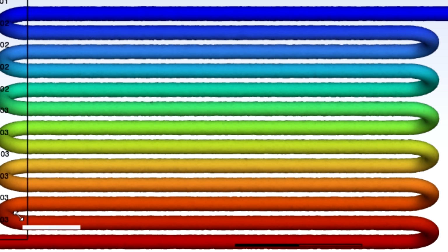So with this one, we'll conclude our today's analysis. This is a very simple analysis of condenser heat exchanger. In this case, we have provided freon gas at the inlet at a higher temperature of 75 degrees centigrade, and finally at the exit, it has changed its phase from gaseous state to liquid phase, and it has come down to a temperature in the range of 20 to 25 degrees centigrade. Right? And this temperature reduction was possible because of fins, and we have provided a huge amount of airflow. Right?